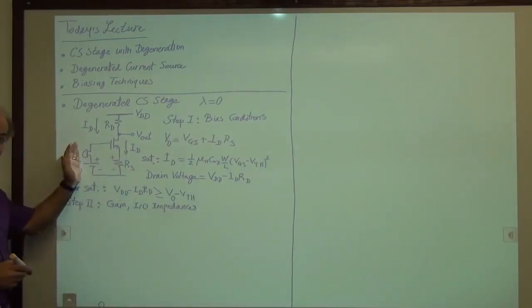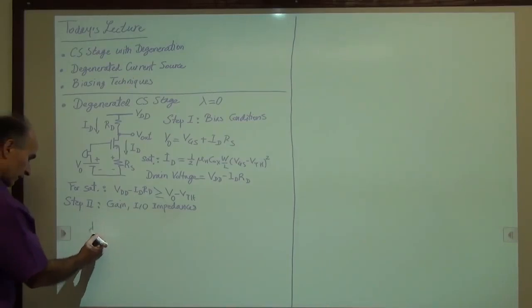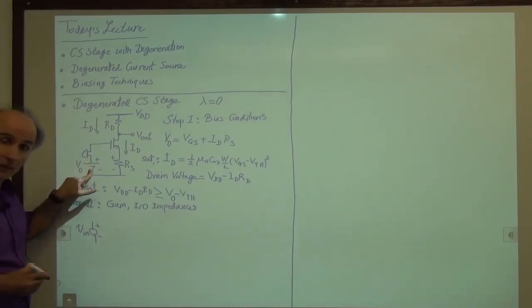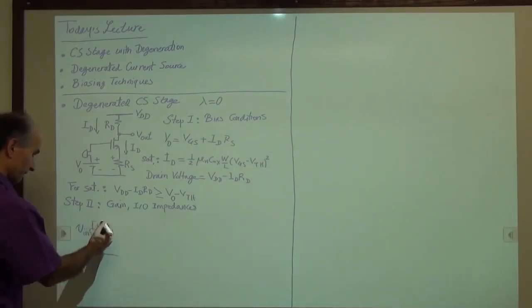No problem. Start from the left side. We replace the microphone with an AC voltage source, assuming that that's a good model for the microphone. Vin. The battery is an independent source. It's a constant voltage source, so it goes to 0.